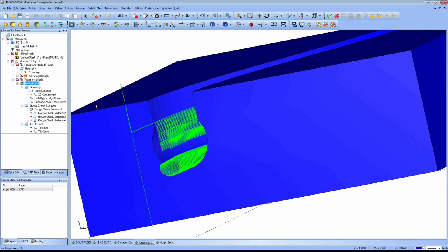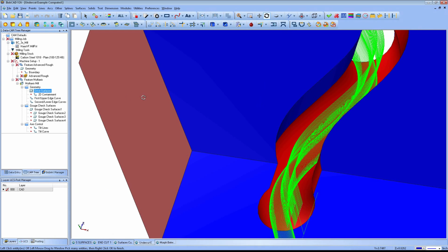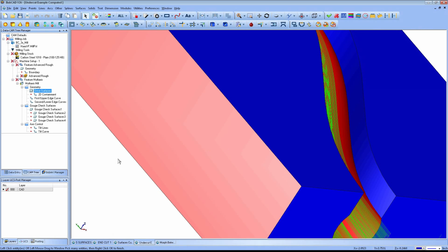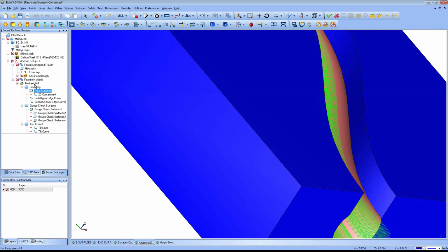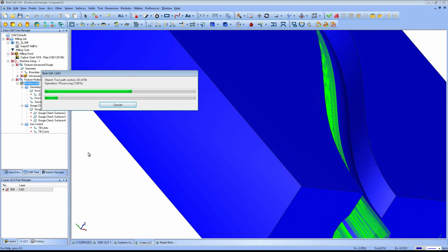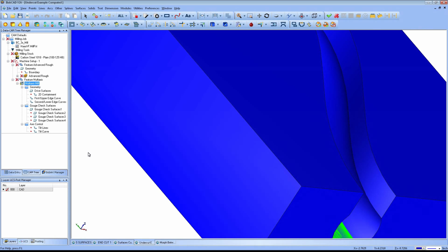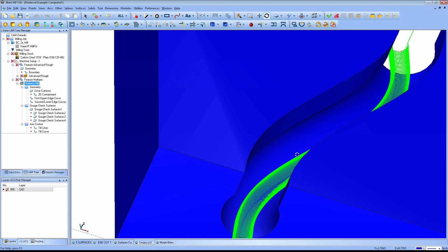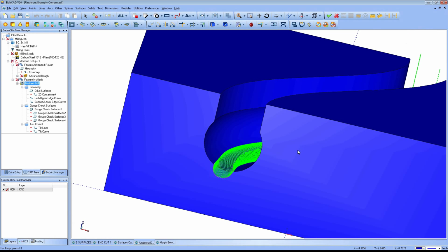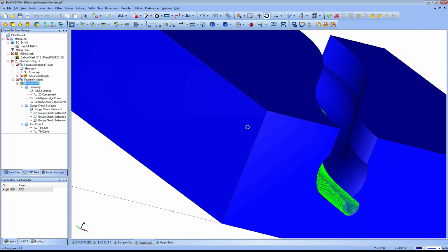You can turn on the roughing, just like we've done in any of the past. Drive surfaces, reselect. I'm going to turn that one off, and that one off. And recompute. And as you can see, if you're curious if that might be a better cut for you, it just takes a couple minutes usually, depending on the toolpath calculation times, to change the surface selection and recompute it. Take a look at the new toolpath.